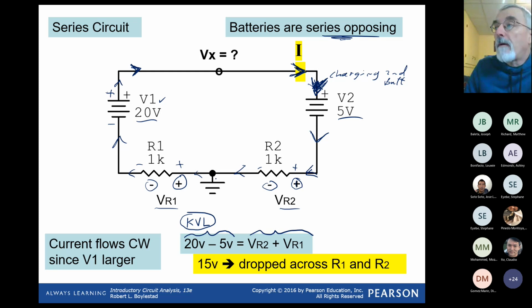We also don't want to worry about ground right now or common. That's just a place we reference. We call it zero, we measure from it. Current, and this is hard for people starting a circuits course to realize, ignores ground, doesn't care. Unless there are multiple grounds, then there's actually a wire there, so it could flow through. But with one ground, current just ignores ground.